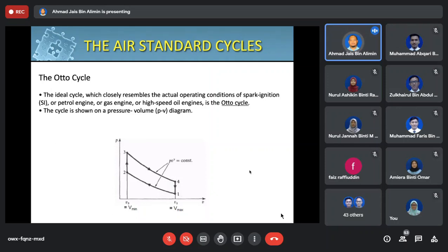And then, when the piston starts to move upwards again, it's where you start to remove or take away the resulting combustion byproduct, the exhaust gas, from the chamber. The piston will move and push out the exhaust gas outside the chamber, escaping through the exhaust valve.